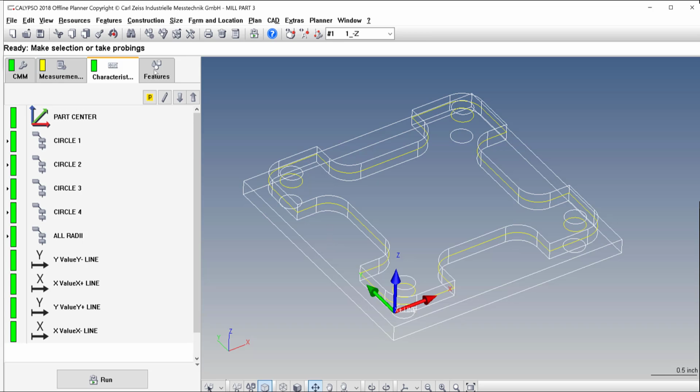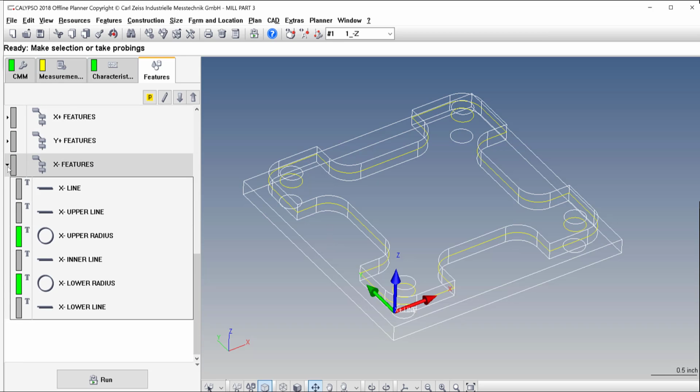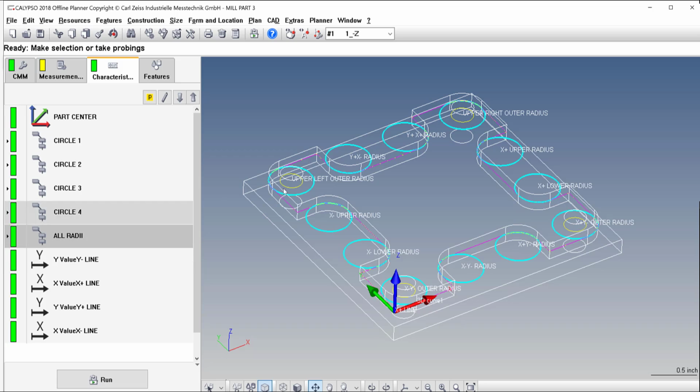Now, if you remember before, I just did all the radii for this example. The radii are tangent here, but there can be instances where somebody wants to know the location of the radius. You're going to treat the radius like a hole. That is definitely something that is debatable. Do you want to not only give this a radius, but give it a location from the 00 at the machine? That's up for debate. It depends on what you need if the part is wrong.